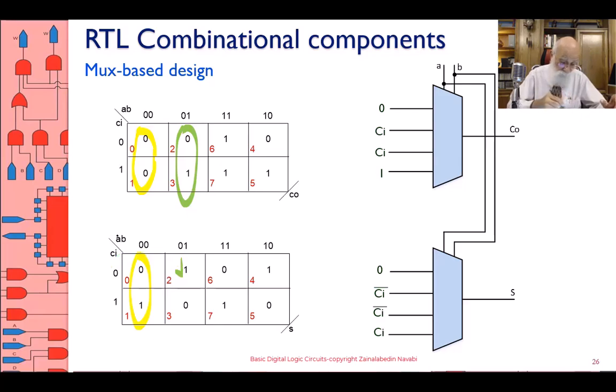All right, so this is what I'm going to do. For each of these Karnaugh maps, I'm going to have a multiplexer, and make the multiplexer so that the inputs of the multiplexer correspond to the columns of the Karnaugh map. Since there are 4 columns, I need 4 inputs for the multiplexer. Since there are 4 inputs, I need a 4-to-1 multiplexer. A 4-to-1 multiplexer requires 2 select inputs. The 2 select inputs become S1 and S0.